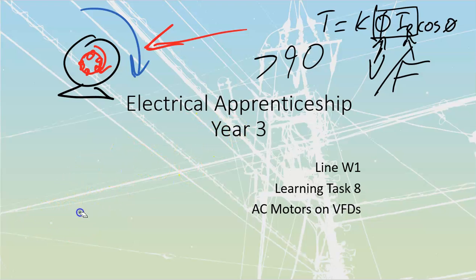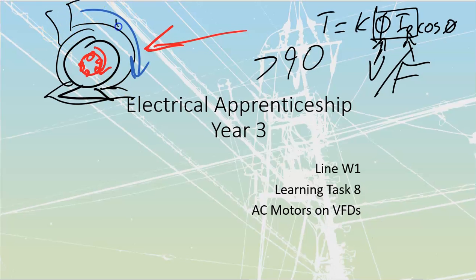First of all, since cooling is reduced, I might have to use a larger frame. A larger frame just means there's more surface area with which to effectively dissipate heat. I might have to provide external cooling, some sort of blower that provides air over top of the motor. It doesn't have to be much, a little quarter-horse motor or something like that, just running a blower fan to keep everything cooled down. And if my motor is running continuously at low speeds, below what it's rated, below 50, 60% and below, I have to reduce the amount of torque demand that I'm trying to pull off of the motor itself. It just has a harder time to maintain that, as well as we've got longer, slower peaks, right?